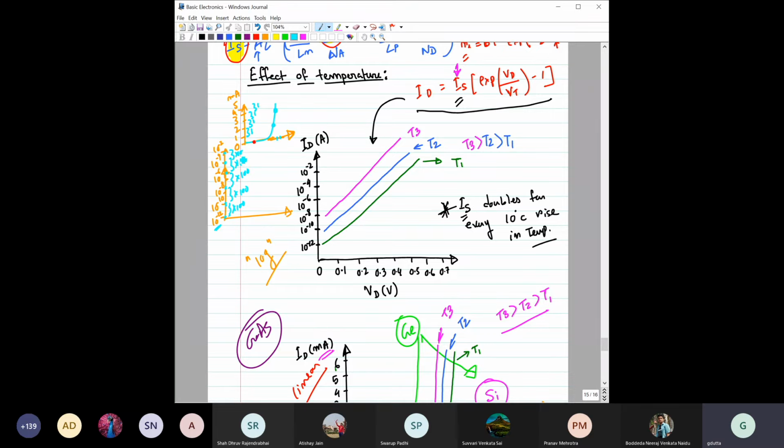So this scale is called the log scale representation. Here, if you now plot the diode, the same thing, you would get a characteristic like this, right? Because here the difference is 1, and here the change is by 100 times. As this is a log scale representation, this characteristic would be the linear one. And for any voltage, even one where you probably cannot tell the value of current, you can get it from here. At any point you can get the value.